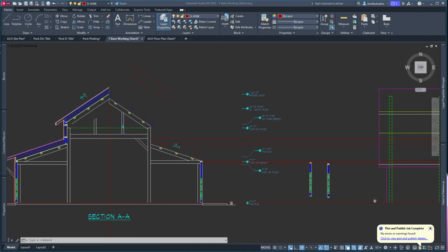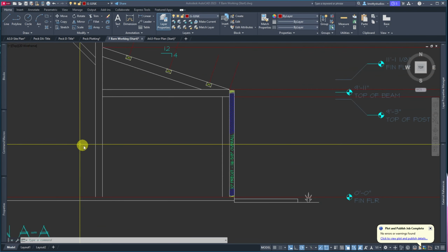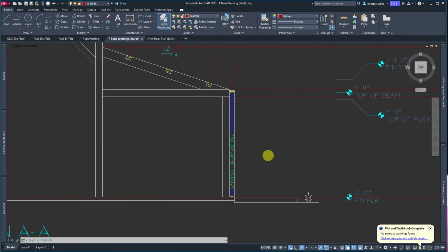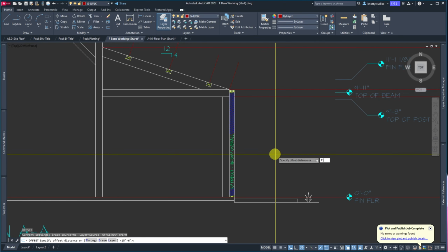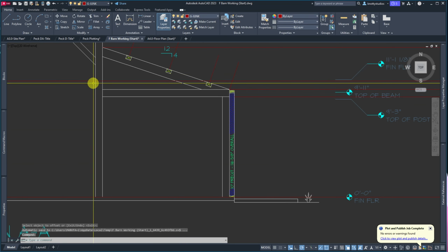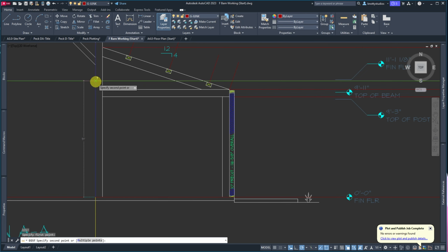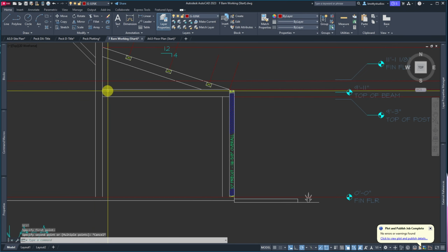Remember, all this is true lumber, so it's not nominal. So 6x8 is actually 6 inches by 8 inches. So zoom in on this area, offset 11 feet. Oh, I must not have grabbed it. Offset 11 feet, enter, up, and that did end up in here. Man, it's low. Distance B, there, that's 11 feet.